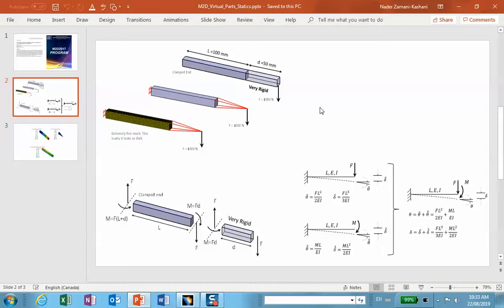So let's take the bar. If you look at the screen on the very top, I have a bar which is 150 millimeters long. It's clamped at the left side, and at the right side there is a force acting, say 1,000 Newton. Now, let's assume that the 50 millimeters on the extreme right is made of a material that's a lot more rigid, bigger stiffness, bigger Young's modulus than the first 100 millimeter on the left side. Of course, it is possible to model this thing as a three-dimensional, 150 millimeter long bar, made of basically 2 types of material.